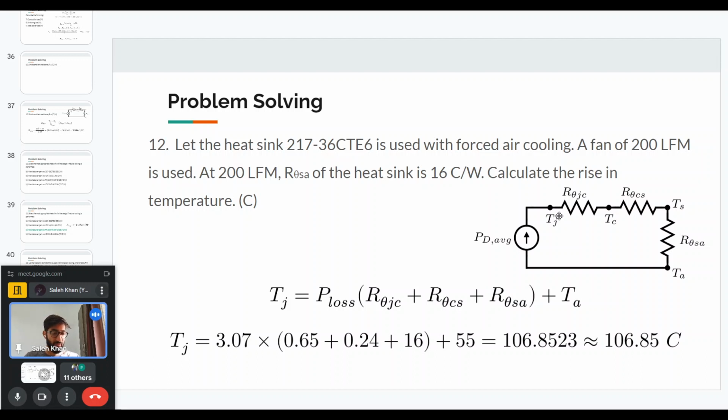Yes, thermal paste. There are different kinds of thermal paste, or what is called the thermal interface material, between the heatsink and the device. That depends on whether you want some electrical isolation, because in some cases the device case is actually connected to the drain of the MOSFET or the collector of the IGBT.